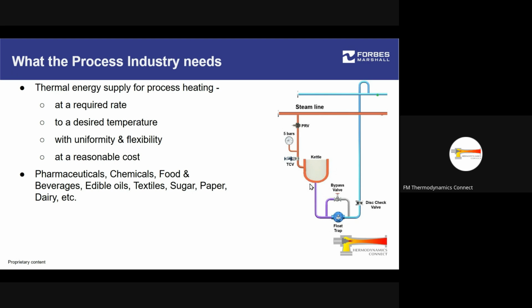Then whatever steam comes in, the same steam actually travels directly out to the exit without doing the heat exchange at all. All right. But if we don't allow this passage, then the condensed water or condensate will remain backed up. So what we essentially need is a specifically designed special purpose valve, which is what a trap is.